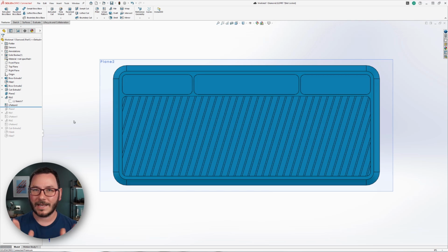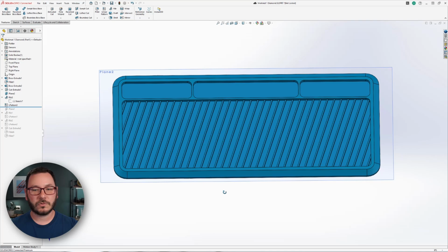But remember, the exact scenario that we just came into with that sketch now finding its bounds up here instead of where it was supposed to is going to happen if we flip this over to the other side as well. As soon as we mirror this over to the opposite side, it now has bounds all over the place for it to find. So there's, I'm sure, lots of tricky ways that we could go about solving that. In this case, we're calling this the easy method. So we'll go with the obvious solution, which is just move up in elevation a little bit and make a new set of ribs. And then we can just trim them back down to where they're supposed to go.